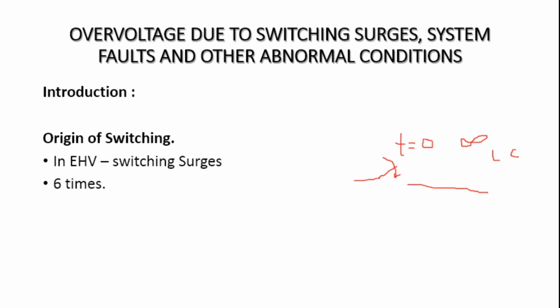Hence, the switching surges may include a high natural frequency of the system, and sometimes they may consist of damped normal frequency of the voltage components. Or restriking and recovery voltage of the system with successive reflected waves from the terminals. So, in other words, what we can understand is that opening and closing of the circuit breakers will cause